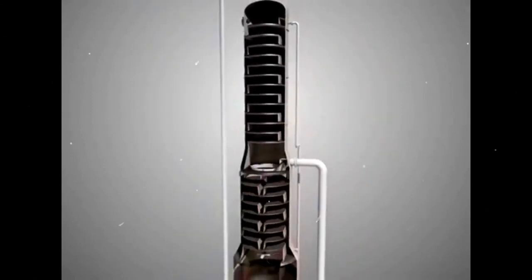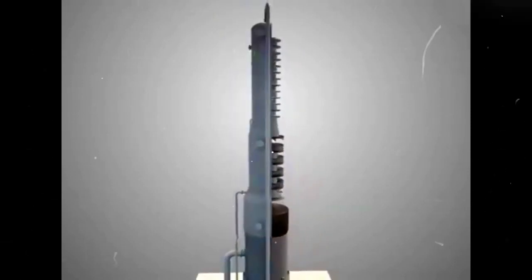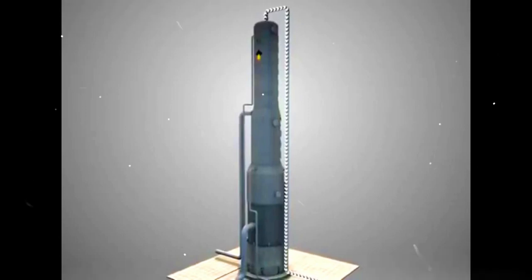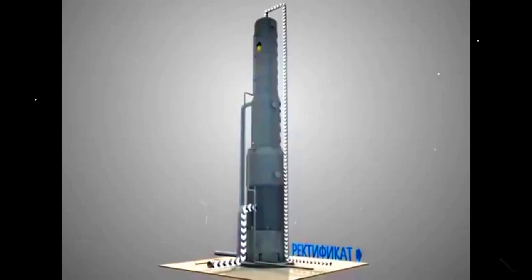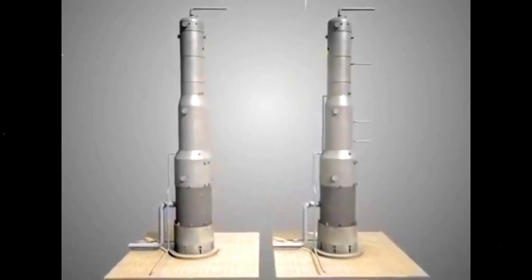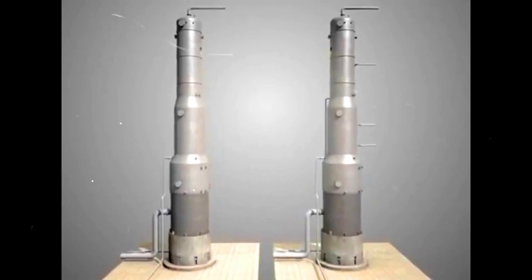The main advantage of structured packings is their relatively low pressure drop per theoretical plate or equilibrium stage, which makes them the most effective vapor-liquid contactor for low pressure, mainly vacuum applications. Packing has a pressure drop that is about 1/5 that of the trays, and is often the preferred choice in cases where pressure drop is the overriding consideration, such as vacuum distillation or where vapor recompression, heat pumping, is used.